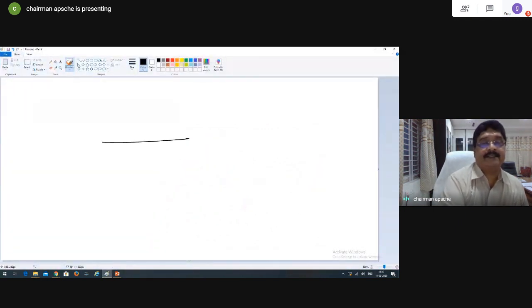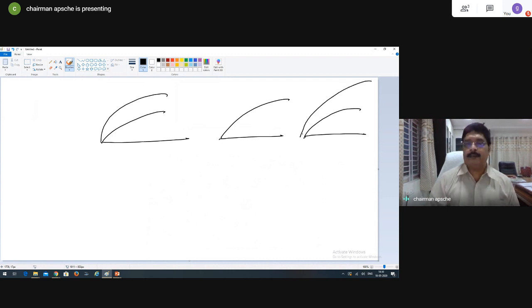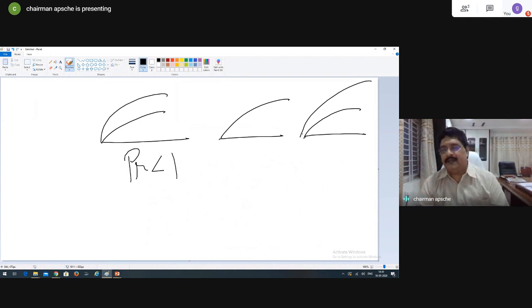So I said this, right? Okay. Now, when Prandtl number is less than 1, what does it mean? Numerator is smaller and denominator is bigger. What is numerator? Molecular momentum diffusion. Thermal diffusion is in the denominator.